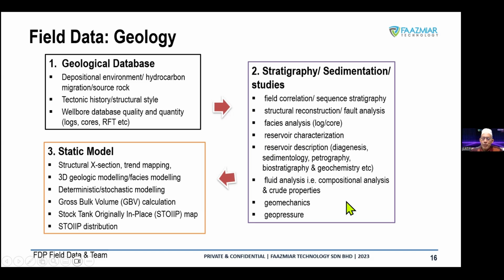At the same time, if we have the opportunity to study, there will be a lot of geomechanics study to do, understanding the stresses around the wellbore. Geopressure, we call it the formation pressure of the area of each layer. So sometimes you have a normal pressure down to, let's say, 3,000 meters, but sometimes you only have normal pressure to 2,000 meters, then you start to have an increase beyond 2,000 meters. So all this information will be captured during the geological analysis.